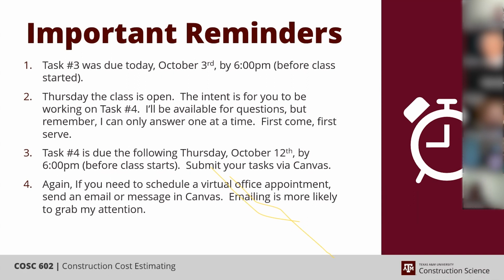Once you're done building it, you really are going to have two 5-foot sections versus one 10-foot section. But theoretically, when you use your unit hour and apply it to all 10 foot, it's going to be the same as if you apply it to 5 foot and 5 foot and then put them both in, because you still have 10 feet times 1.5 hours per lineal foot. It ends up being the same.